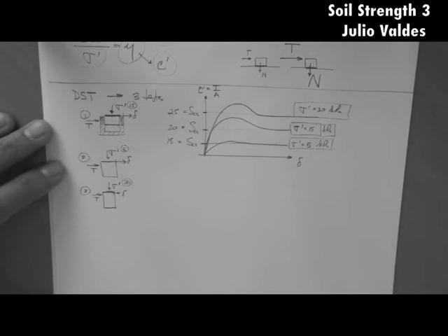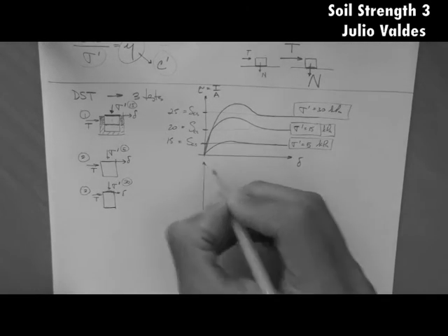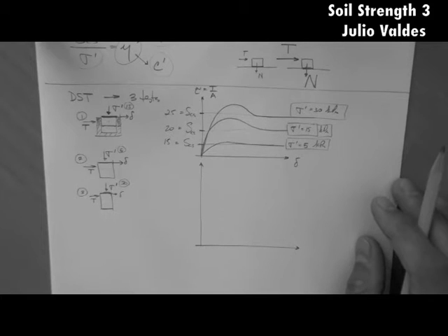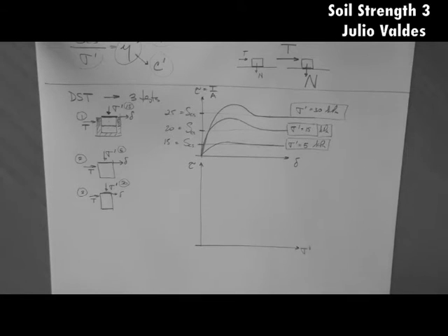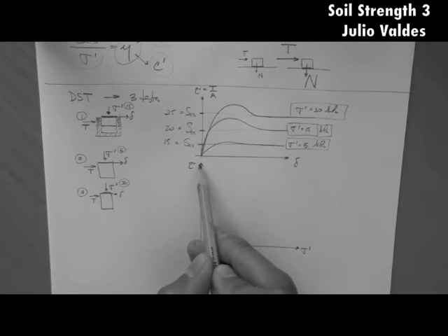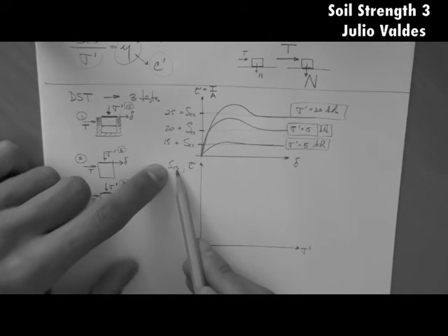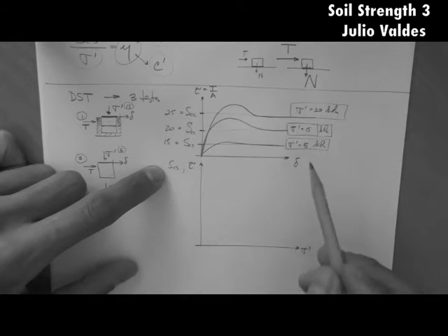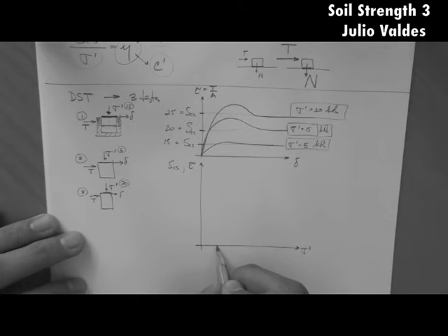We're going to do that now. So, you take the data and you extract the coordinates for points that you're going to plot in the Mohr circle space. Effective stress, tau. Instead of tau, what we can do is put a comma and say strength, because strength is a tau. So we're going to plot strength, the three strengths, versus the three effective stresses. Very simple.